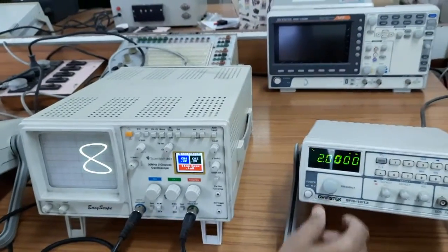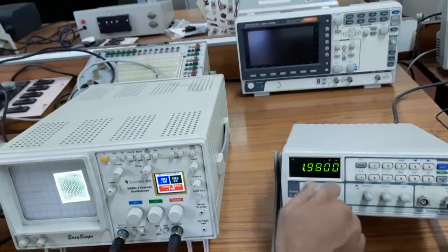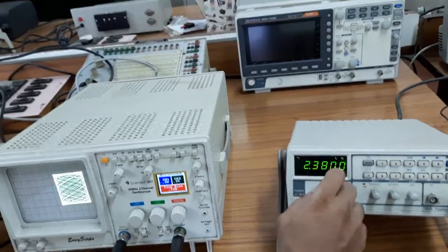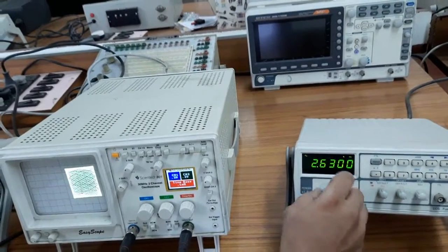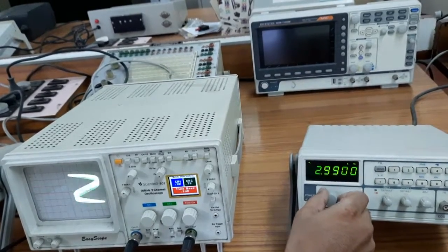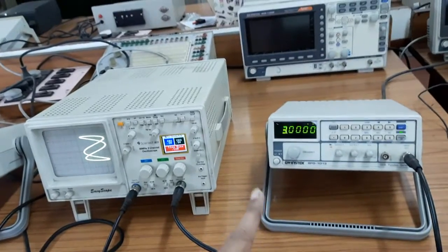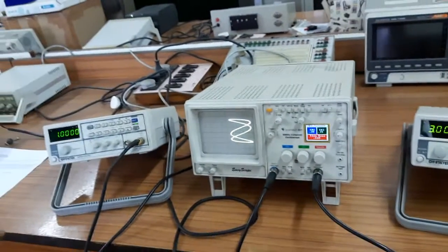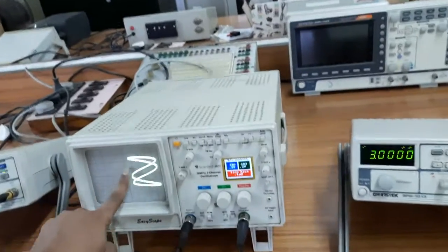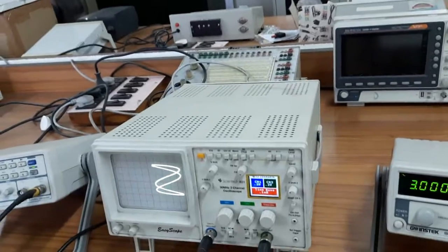Some more figures I want to show you. So it is a 3:1 figure. Just follow. Here it is 3 kilohertz and here it is 1 kilohertz. And the figure also says that horizontally 1 point touches and vertically 1, 2 and 3. So it is 3 times the frequency.